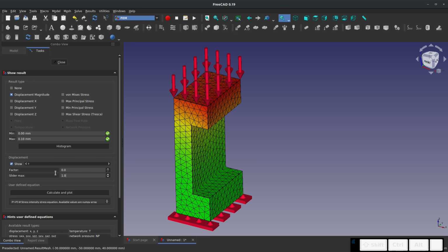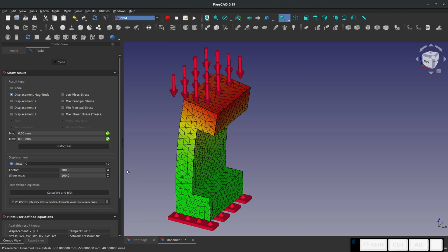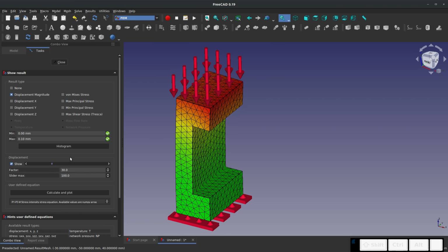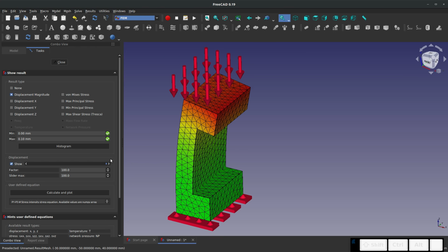And when you do an analysis, one of the first things that is good to look for is, one, balance your forces. Make sure that the reactive force equals the input force, so that you know that everything's accounted for. But you also look to make sure that this movement is realistic. Is this moving in a way that I would expect? And if it's not, that's a great way to catch errors in your analysis.